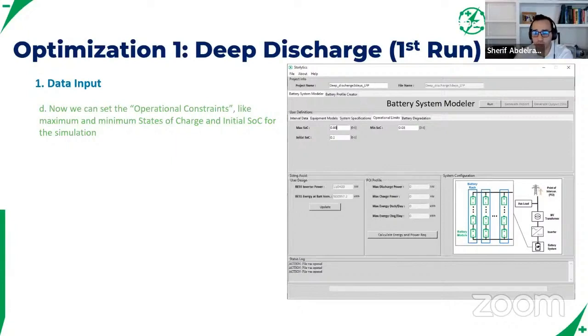That's why with all LFP cells out there, it is very difficult to get the full range of that SOC range, unless you literally just performed a balancing cycle, which differs from one OEM to the other.